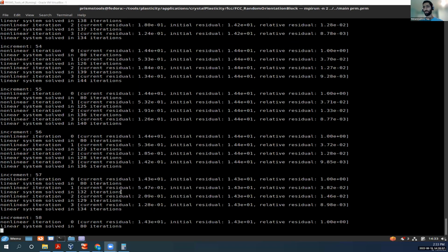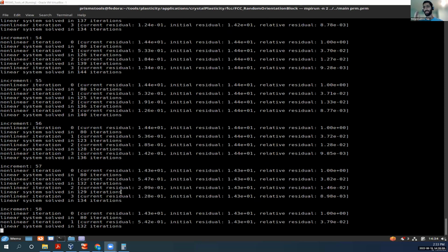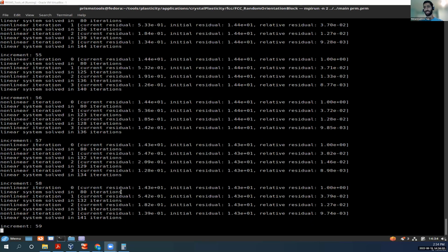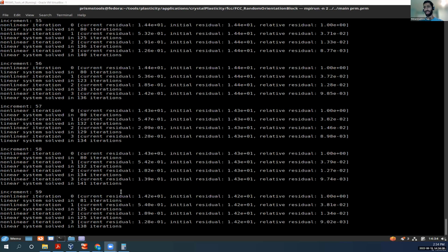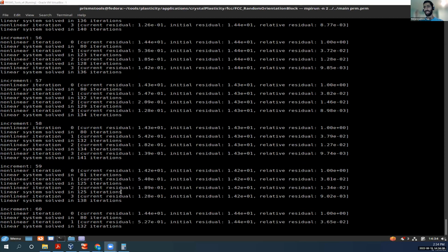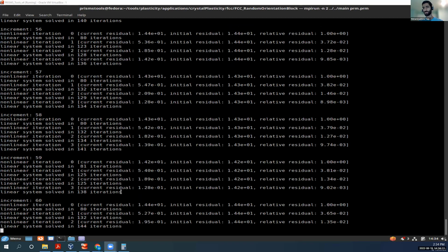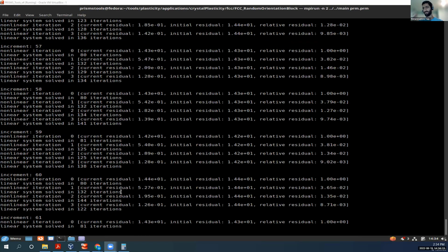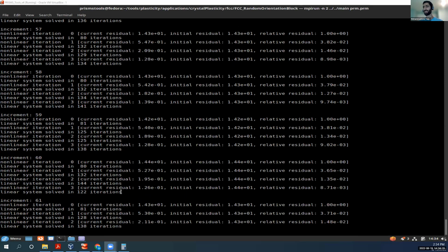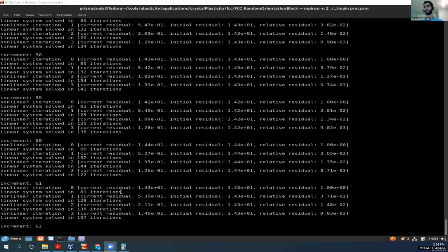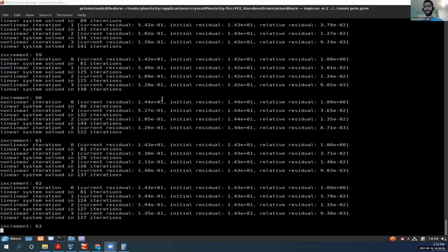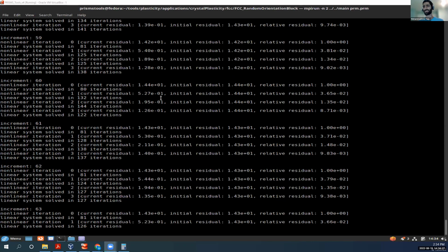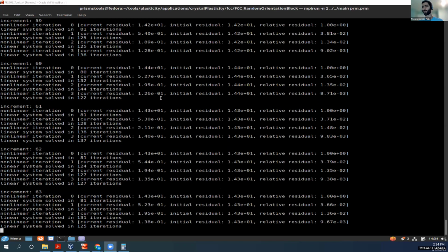But the bottom line is you need to install and compile LAPACK or BLAS or something like MKL, which they have already compiled as a module. And you need to have PETSc, p4est, and deal.II along with those packages for PRISMS-Plasticity. I have an installation I can share with you, but even for our clusters, when we change it, it doesn't work for another cluster. So it's not easy, honestly. Anyone interested, I can share that one with them, but it's probably not what will work for theirs.